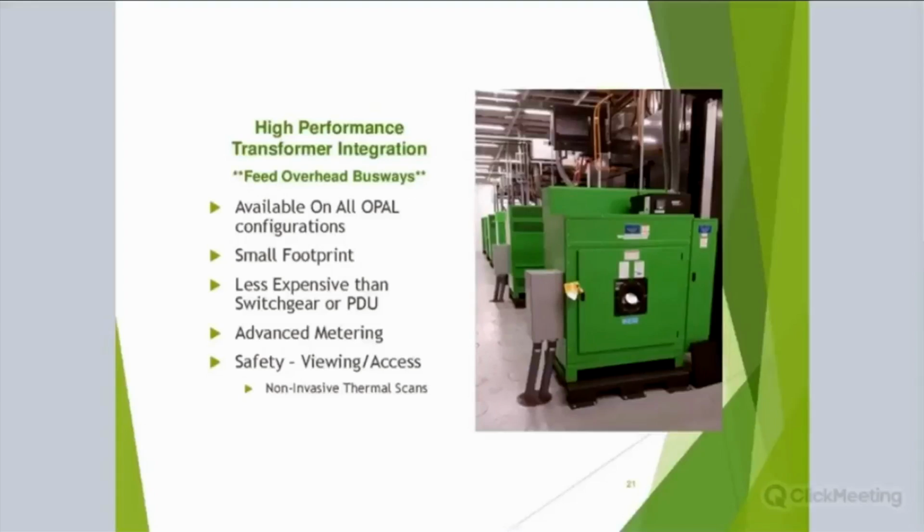So if I have a 480 volt circuit to the transformer, you can build the transformer to provide one breaker that supplies a 120/208 volt load. Another breaker may supply a 240/415 volt load. So that's more specific application, but that is used a lot on industrial facilities and what have you.